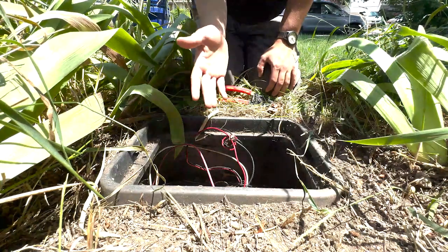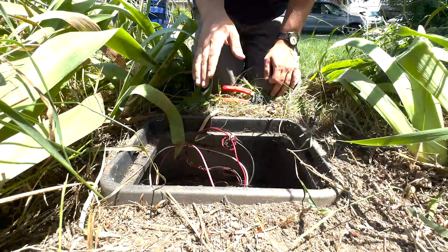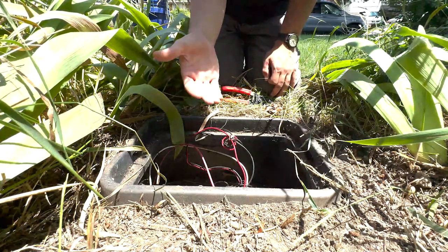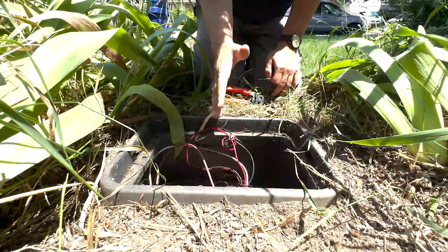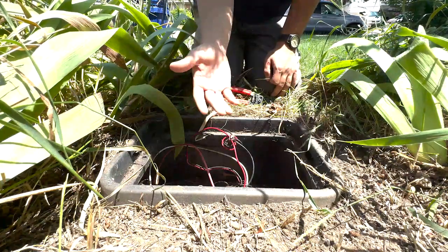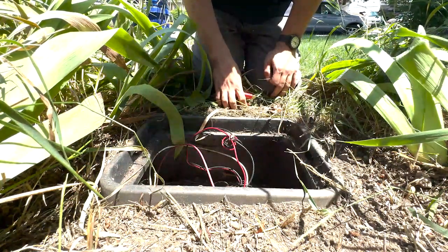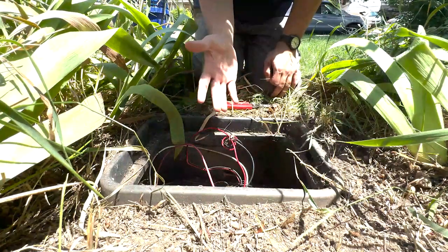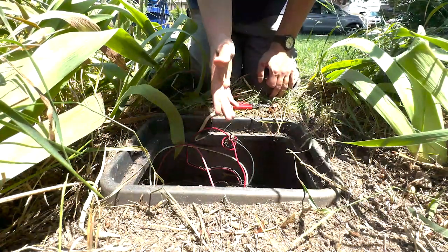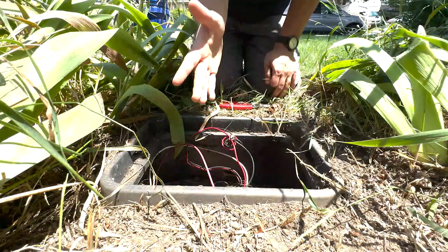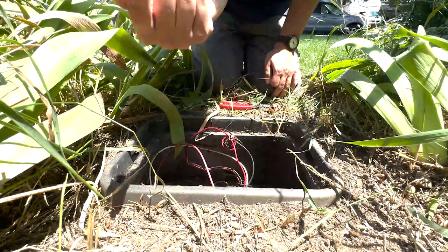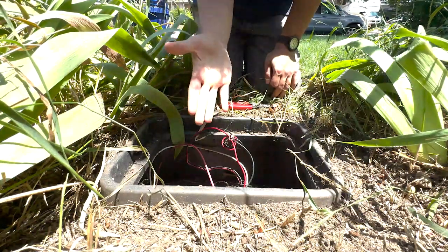Now that we've checked our flow data for today from the controller panel, we're ready to come outside and try our tap test from the field. Now, the tap test from the controller was testing if our controller had the ability to locally read flow data. Now that we've ensured that it does have that ability, we can come out to the field and test that our wire loop has the ability to carry that flow data to and from the controller.